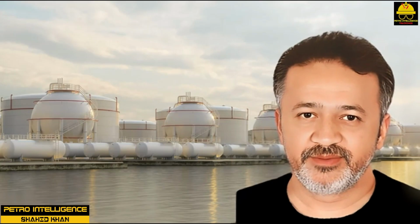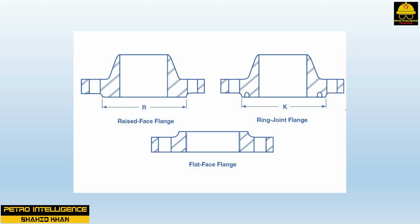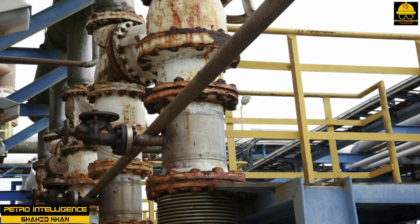Flanges. Flanges are used to connect piping to equipment or where the piping may have to be disconnected. They consist of two mating plates fastened with bolts to compress a gasket between them. The three common types are shown in picture. Flat face flanges are generally used to mate against cast equipment, where bending from tightening bolts might break the flange.